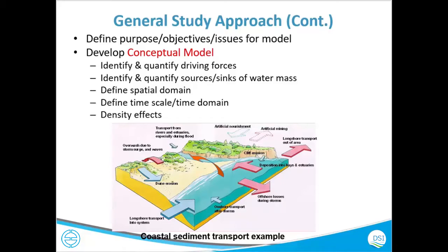In EFDC, it has equations where density, temperature, turbidity have a relation. If you go into the source code, the temperature dependence of density is explicitly stated there. If you're using only temperature, it will use the equation that considers only temperature. But if you have both salinity and temperature, it will lump both together, and then the density will be calculated.